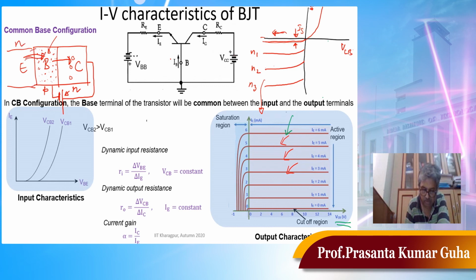Those electrons will see the reverse bias, the positive terminal of the battery connected to the collector, and they will be dragged to the collector. So we will certainly have current, and the amount of current depends on how many electrons are present at the base or manage to cross the base collector junction. In a nutshell, the more the IE, the more will be your IC.